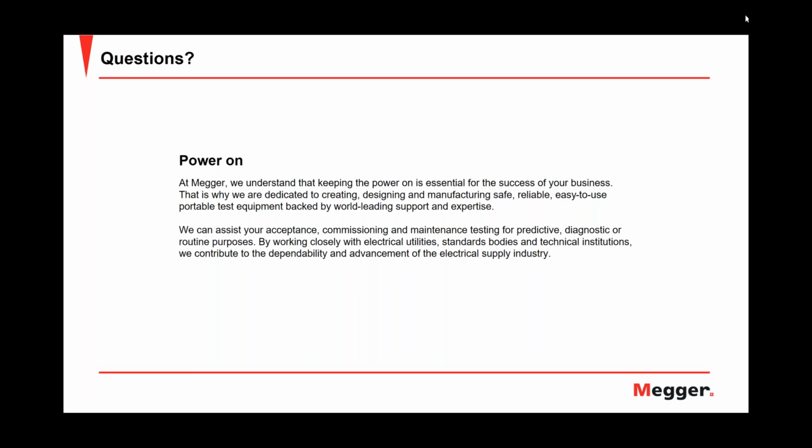But there is also always another way to verify this. If you see an open and you're not sure, is it the end? Is it an open conductor, or could it be an open neutral? If you don't know, you go to the other end and you short the conductor to the neutral. If you see no change on your TDR screen, you're not looking at the cable end, but you must be having an open, either open conductor or open neutral. That is the confirmation of that situation.